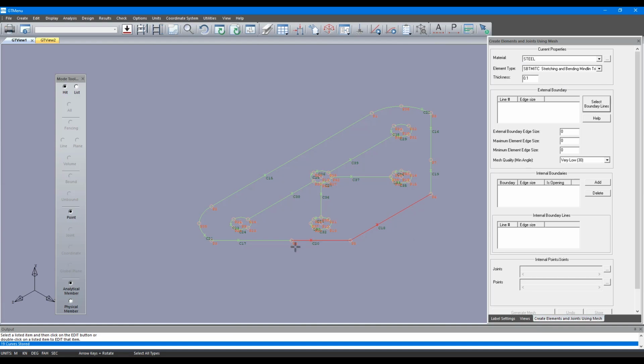So you just have to select the X's here to define that as the outer mesh boundary. Once we've done that, it'll show you all the boundaries that form the outer boundary of this plate. Now here I'm going to specify some parameters. We'll take care of that later.